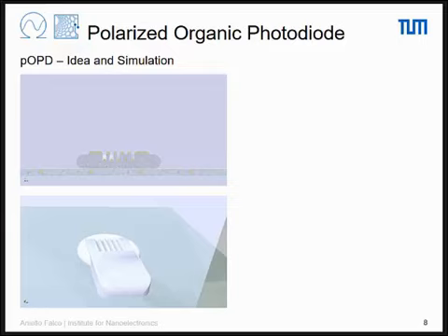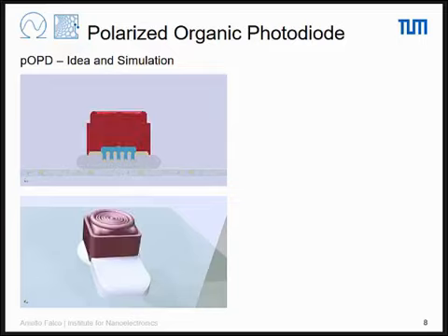In the 3D version here, you can see that it's not only evaporated in the middle where the lines were, but it goes also a bit out. In this way, we can use it as an electrode. We can deposit PEDOT:PSS, which is the material that we normally use to adapt the work function of the metals to have a higher work function. And we deposit the bulk heterojunction, so the semiconductor itself, and then we evaporate a calcium aluminum layer on top.